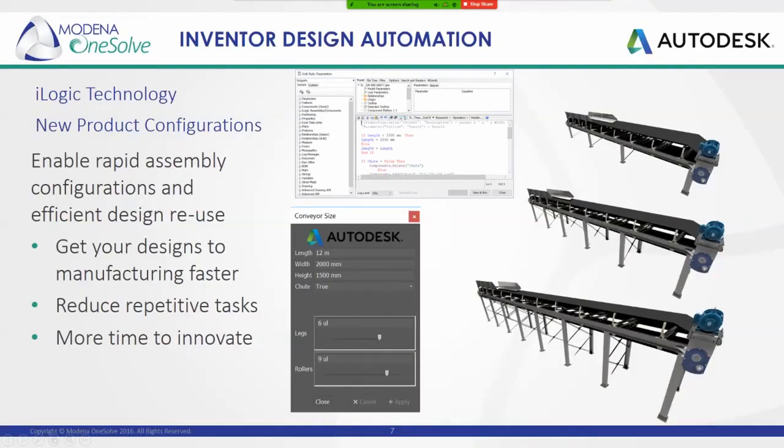And just below that, we have these intuitive manipulators that can be dragged in order to include extra legs or reduce amounts of legs and rollers for the entire conveyor. Once these settings are configured, the design will be created. Once the changes have been made, the model will update accordingly. And to expand on this, we could add additional buttons, one to update the drawing and dimensions, and another to update the bill of materials and export it to a document that can be used with an ERP system to generate a quotation. Now, let's have a look at some of this iLogic in action.